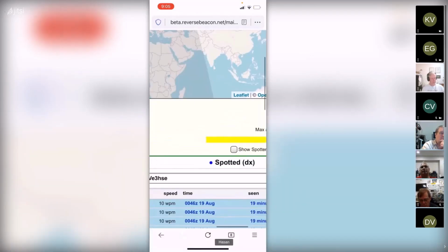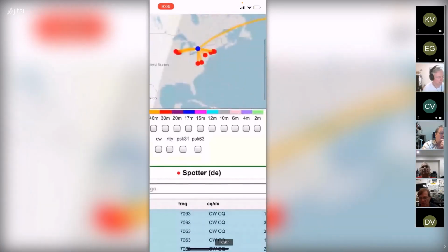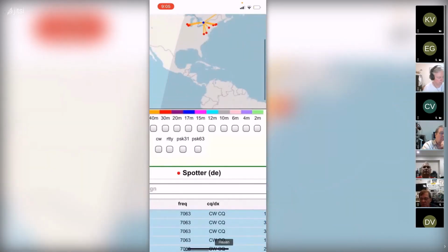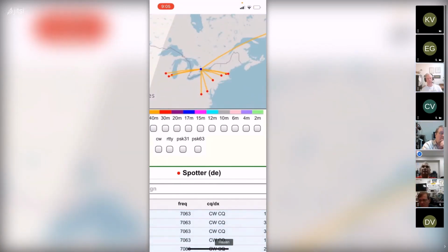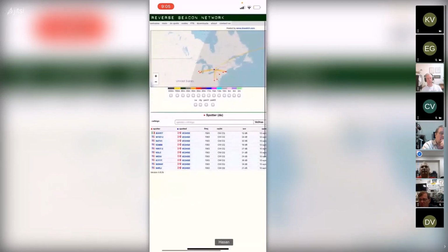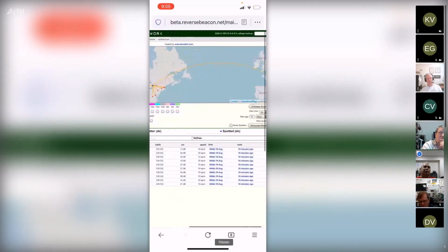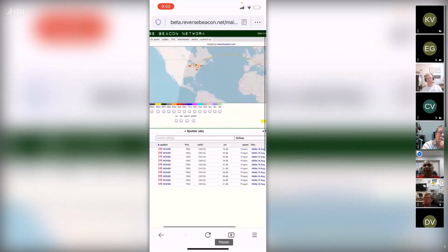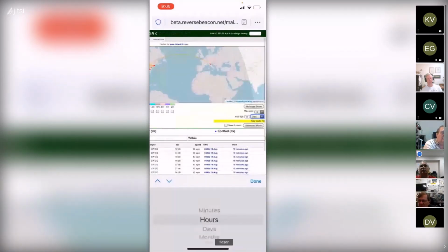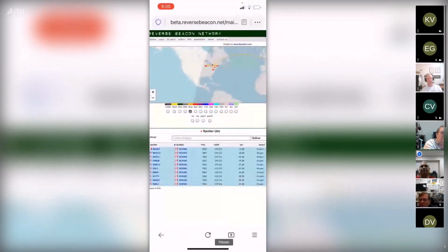Well, yeah, but okay, so I guess I should just get a better ground plane, and that's how we'll get better radiation angles. Like this is probably 50 degrees. Yeah, Hassan, the way you could tell is to go look at an ionosonde. Go look up to see what frequencies are open, what's happening on 40 meters, and that'll tell you whether you do an NVIS or what's going on, because that's telling you what's going on in the atmosphere, right?